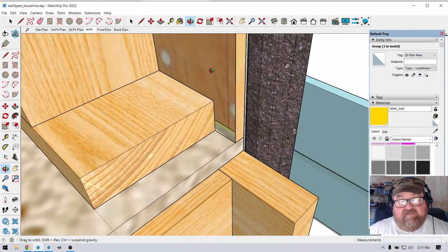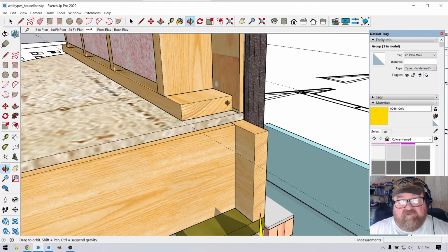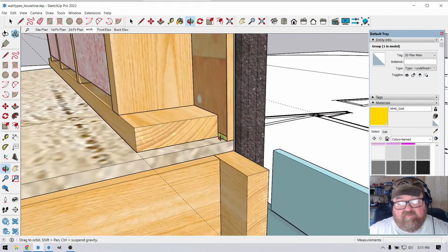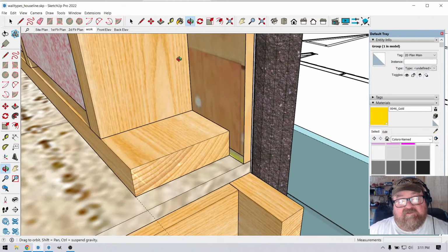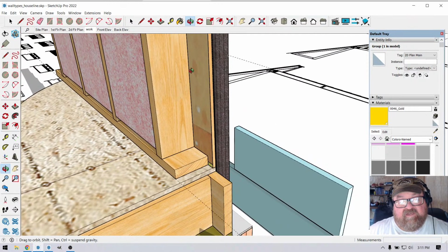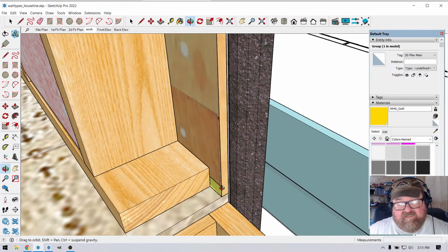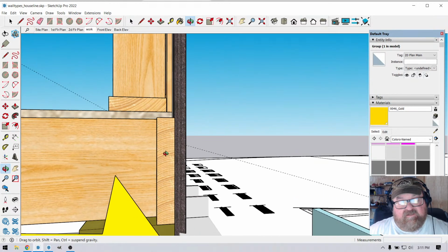The other thing is the sheeting serves a functional role in the wall. It actually braces the wall. The bottom of the sheeting is supposed to be nailed to the bottom plate, and then to all the studs in a nailing pattern. And if this is a shear wall, you're supposed to have nails every 6 inches into the bottom plate. Now, guess what happens if you run this sheeting out here?